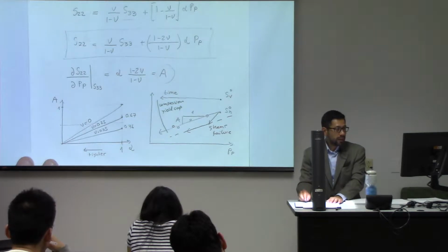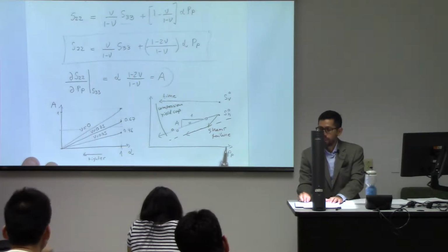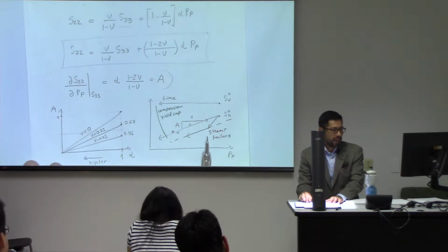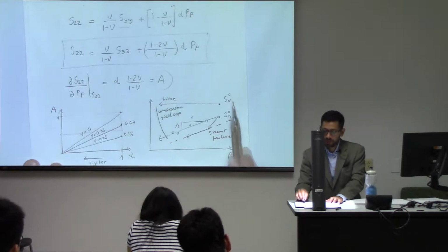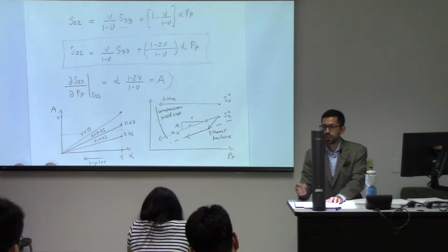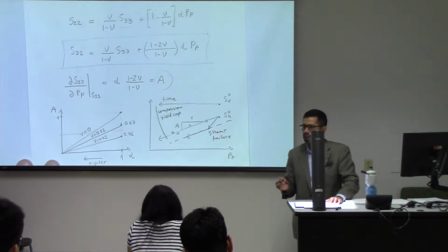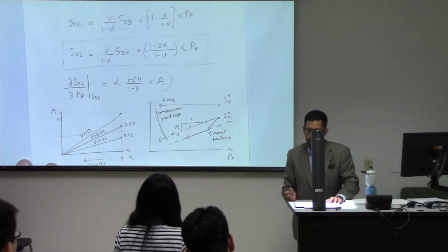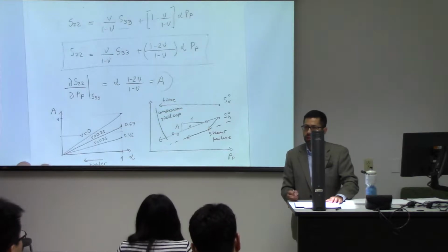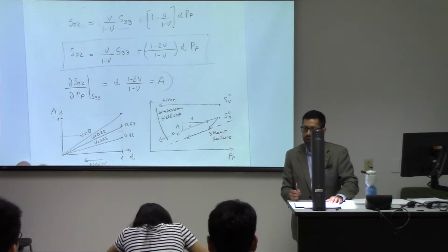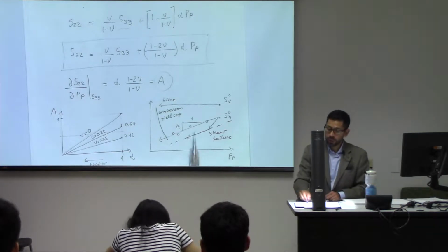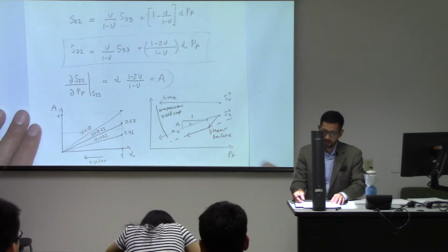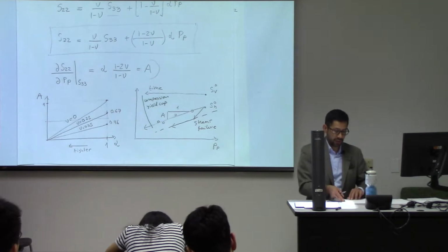So these plots are very useful, and they allow you to see what is the evolution of total stresses as a function of pore pressure, but total stress is not really the right parameter to plot in terms of rock failure. So instead of that, let's try to see what is the equivalent of this plot, but in terms of effective stresses.